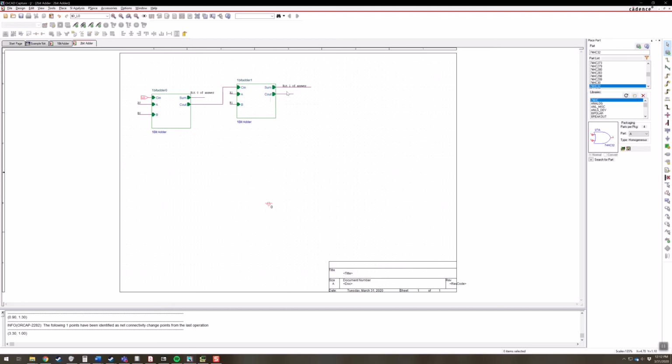But then if you were wanting to do a 4-bit adder, well, we'd have to cascade 4 of these stages. Now, the next question becomes, how do we test all of these things? Because trying to create digital stimuli, like we did in the first video, for every single one of these inputs is going to be pretty challenging because you've got really 16 times 16 possibilities.